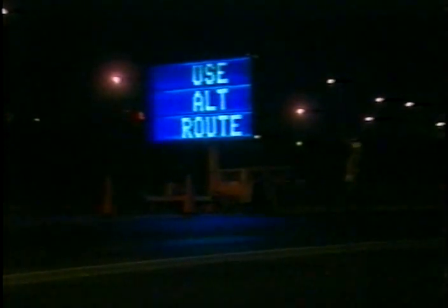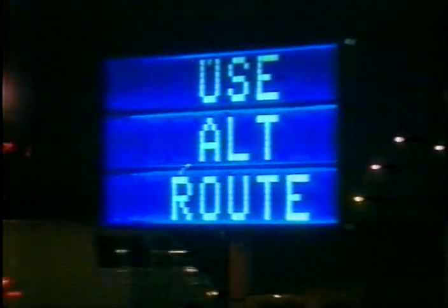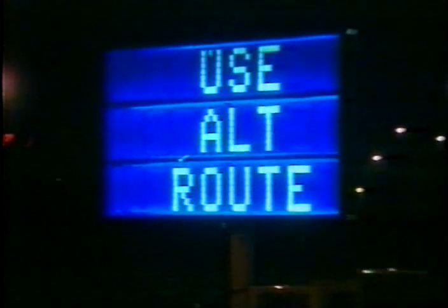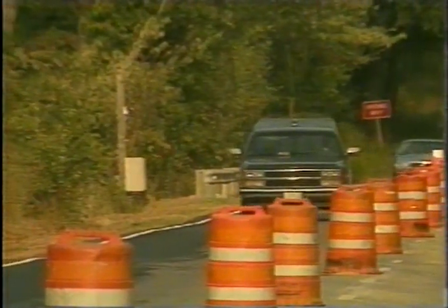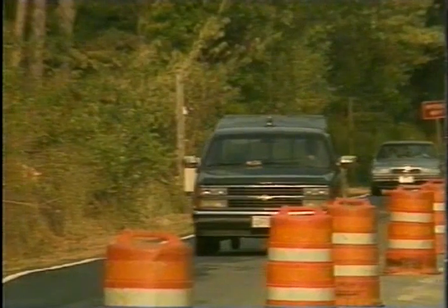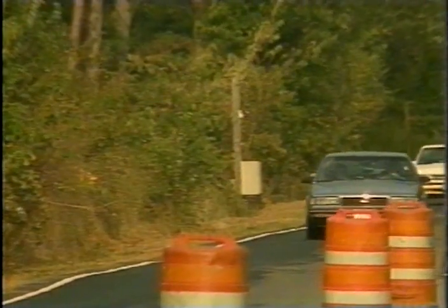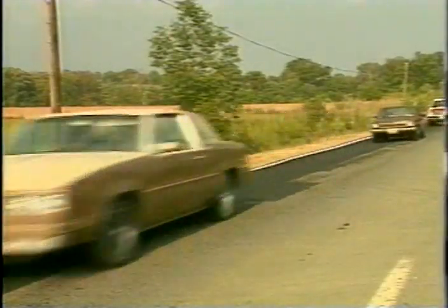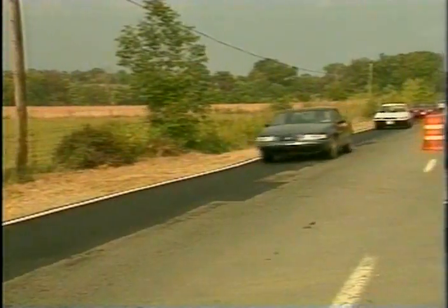There are also several basic ways to maximize convenience, such as advising the public of major anticipated traffic delays prior to start of work. Changeable message signs work very well for this purpose. Avoiding scheduling work during peak hours and holidays. Closing only lanes that must be closed and reopening them as soon as is practical. Avoiding severe speed reductions. Preparing an alternate route plan in case of an accident or other emergency.